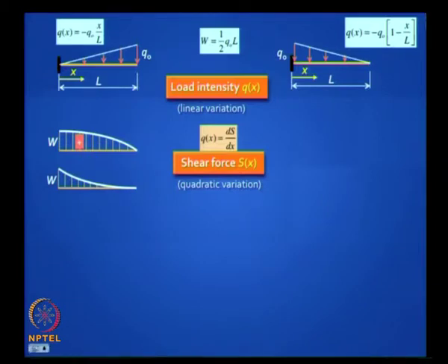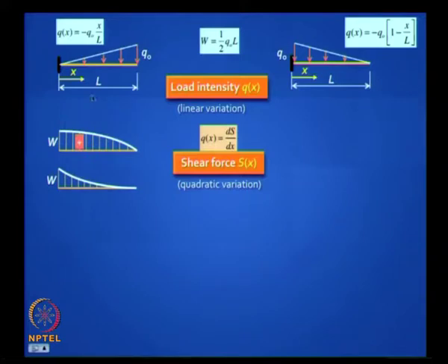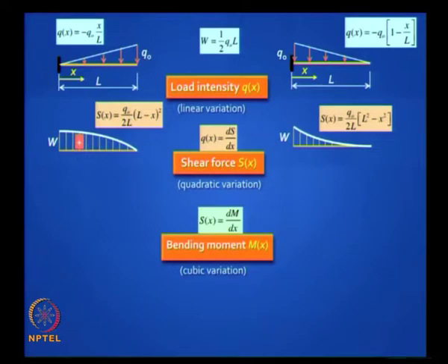So let me use this pointer. Right. So you will find that the slope of the shear force diagram, here the slope is 0, it is tangential, here must be the load intensity which is 0, whereas in the lower case there is a definite slope. So actually this diagram belongs there for the other beam. So you can see where the slope is 0, there the load intensity is 0, and where the slope is maximum, there actually the load intensity is maximum. So it's a very easy way of understanding the relationship, and you can write equations if you wish.